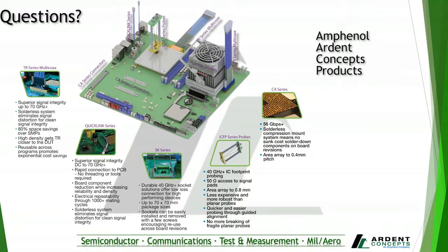And the first one is, what environmental shock and vibe or other testing has this product been tested under? So that's a great question. I may have missed the specification earlier. So our connector systems have been tested to MIL standard 202. So they've gone through shock and vibe, salt fog, and temperature testing, and have passed all to the MIL 202 standards. We're happy to send that report out to any customers who request it.